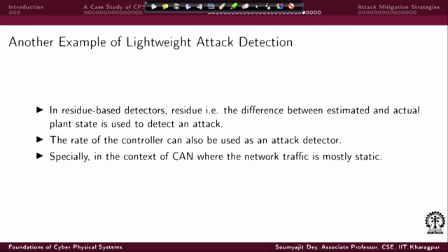If that is the case, then if an attack is happening at those points, it will be detected, because when I check, I figure out that there is a CAN message with an ID, because of the attack, but this message was not supposed to be there, because the controller knows this is not a time when that value is supposed to come.